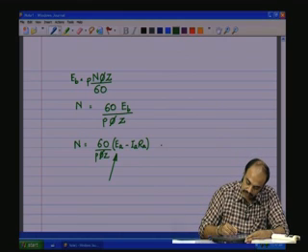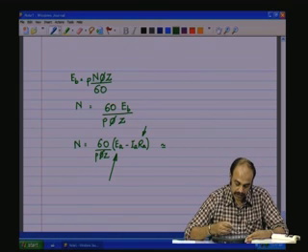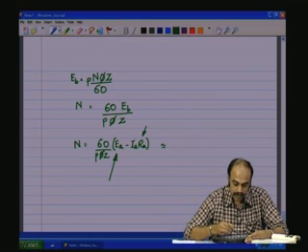In many cases, we can approximate, as this drop will be low at higher speeds. For a given power, as the speed increases, the back EMF is going to be higher, and therefore, the armature current IA will be lower, and RA is already low, and therefore, the IA RA drop at higher speeds will be negligible compared to the applied voltage.